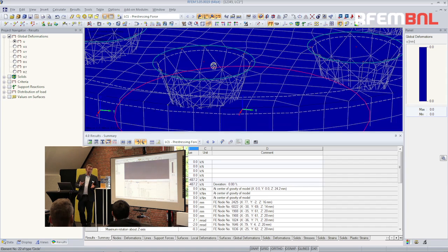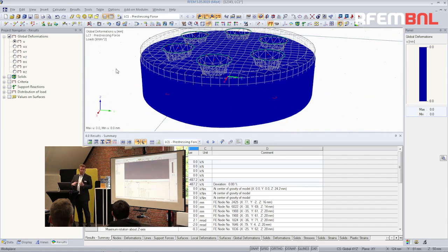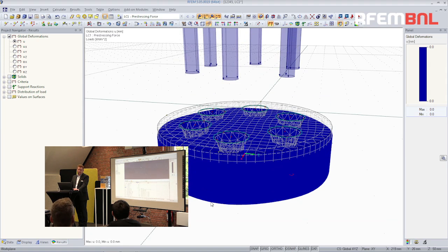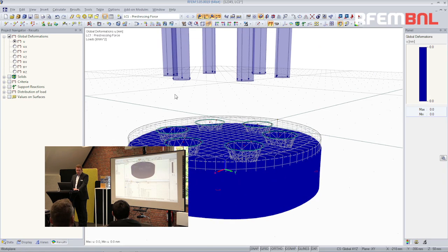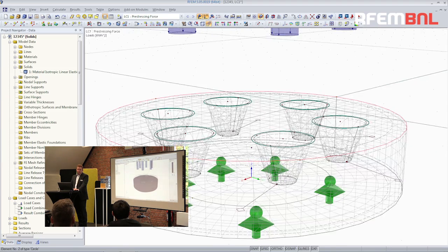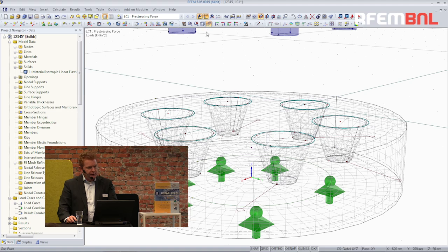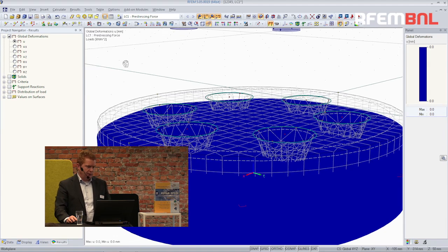It's not perfect yet, it's not 500 yet, but it's much better. So the meshing has influence on how we apply loads in this case. Be careful about it. So this is what I always check, to have a relatively good mesh and apply the load correctly. And you see here, if you look carefully, that the mesh is denser around these areas.